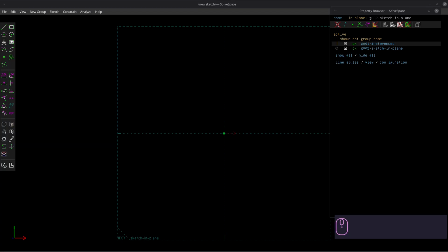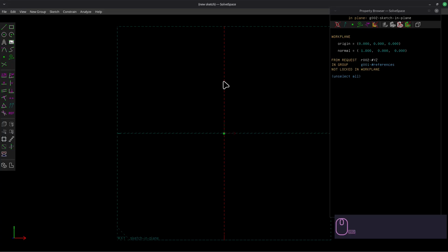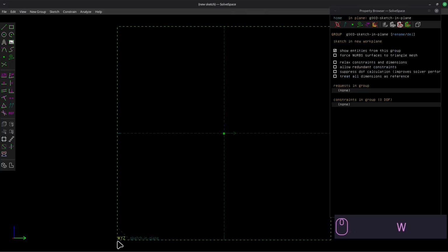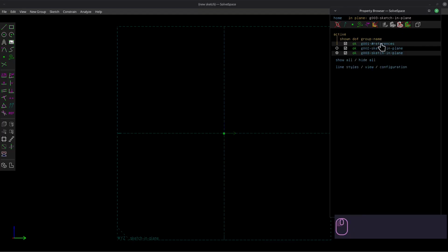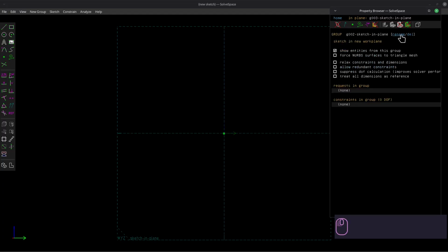this example. In this project, we sometimes want to draw in the YZ plane, which means we need to rotate the editing view to that plane and create a new group aligned with the desired plane. The easiest way to change planes is to mouse-click the desired plane and press Shift-W. Here we go. Press that plane, Shift-W. Notice how we're now in the YZ plane, and the blue arrow is pointed upward. After we've created the desired YZ group, it's a good idea to delete the original group to avoid confusion and redundancy.